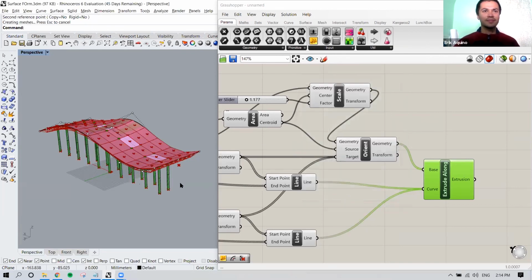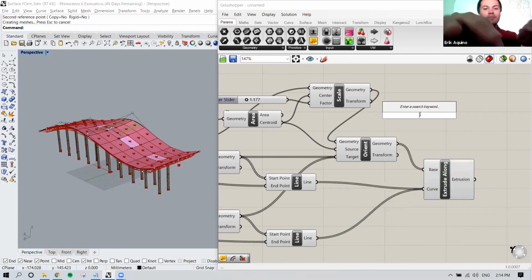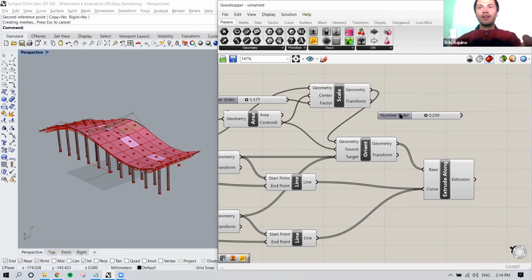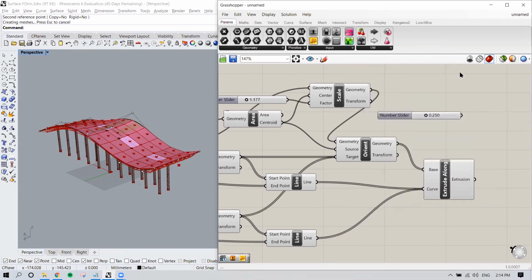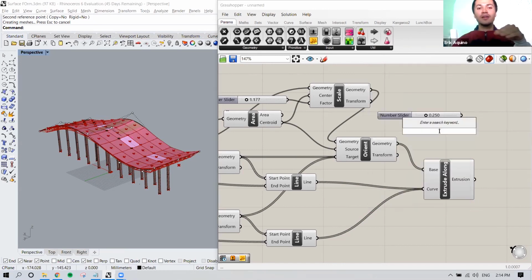Okay. I have one really quick question. When I make a number slider, do I type number slider and then enter? What I do is, yeah, you could type number slider and then Enter. You can adjust it by right-clicking and going to the edit dialog. But if you wanted the quick way, you could insert a number that's in between a range of, or a multiple of 10 range. So you could do 0 to 10 would be 5, or 5 would be within 0 to 10.